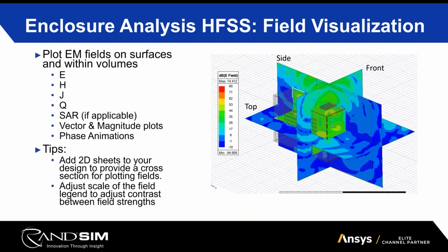We're focusing mostly on 5G, but if EMI is another concern that is common in your design space, we have a whole other suite of EMI specific test setups and applications that HFSS can help address as well. Things like radiated emissions, conducted emissions, susceptibility, bulk current injection, electrostatic discharge, etc.